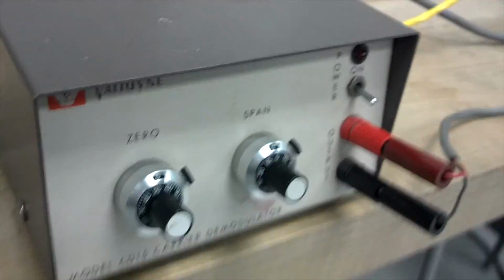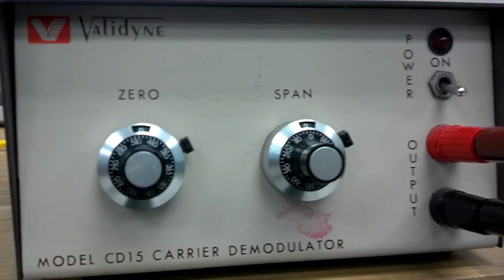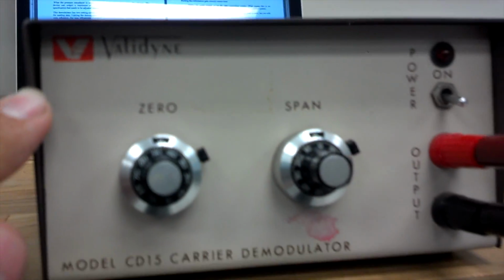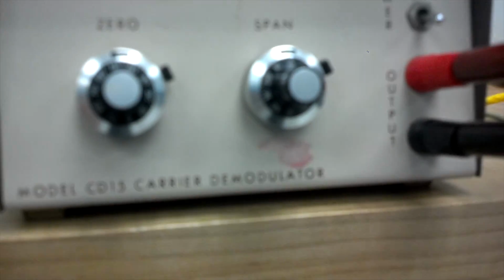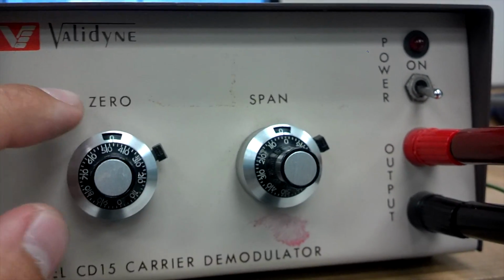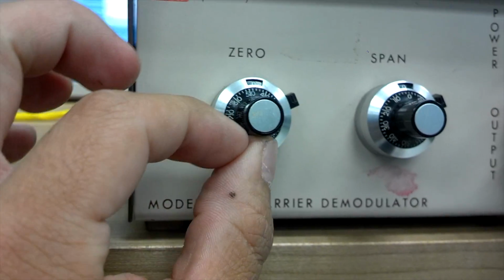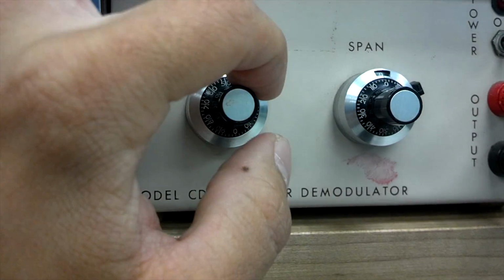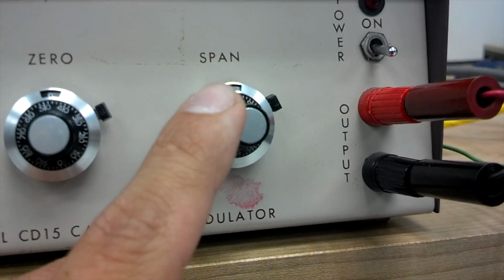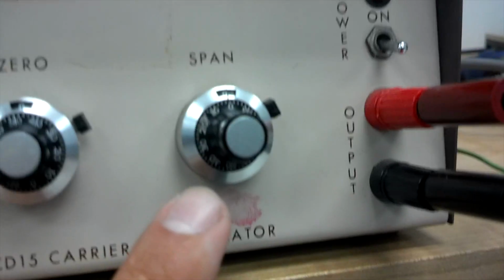The transducer has a 0.005% per degree Fahrenheit zero shift specification that needs to be adjusted because of temperature change. This demodulator has two settings called 0 and span. The 0 is used to set a reference 0 for reading data. Linking the demodulator to a data acquisition system can do this. To set the 0 reference, the 0 adjustment is rotated counterclockwise or clockwise until the value without load is equal to the neutral point. The other setting is the span, which is used to adjust the range of values.